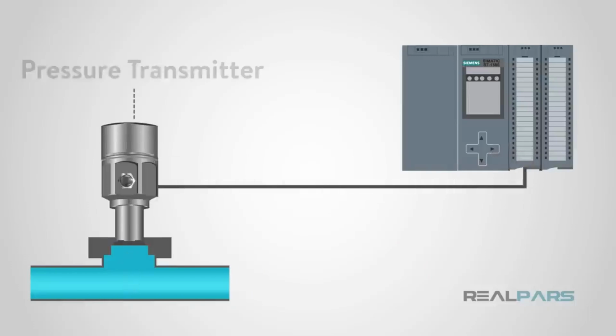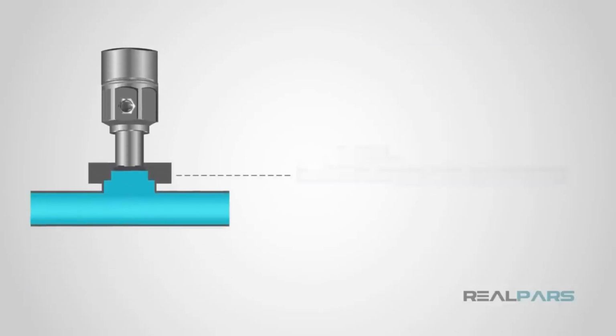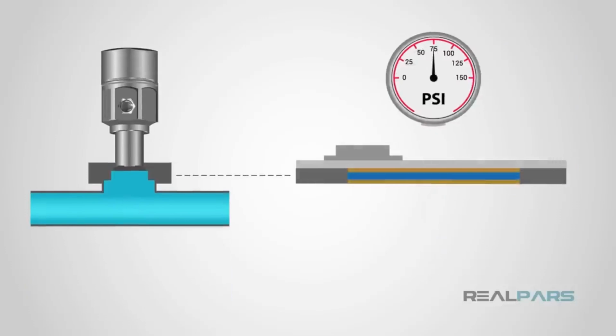These are also commonly called pressure transmitters because of this. Two common signals that are used are a 4 to 20 milliamp signal and a 0 to 5 volt signal. Most pressure sensors work off of the piezoelectric effect. This is when a material creates an electric charge in response to stress. The stress is usually pressure, but can be twisting, bending, or vibrations. The pressure sensor detects the pressure and can determine the amount of pressure by measuring the electric charge.